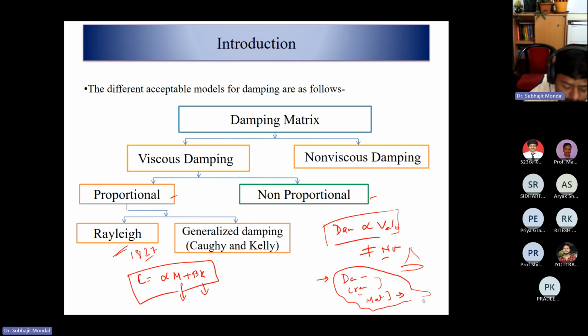Okay, so he proposed a very simple model. He said, let's assume the damping is basically affected by the mass and stiffness, so you can model the damping in terms of mass and stiffness by considering the two terms alpha M plus beta K. Now what is our role? Our role will be to update alpha and beta, because we have already updated the mass, in the sense that we can measure the mass accurately, so we kept that mass there. We have updated our E values, E1, E2, and G12, and we get our K value with good accuracy. Now we are going to update alpha and this beta term so that we can model the damping quite accurately.